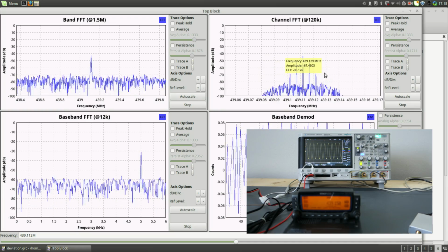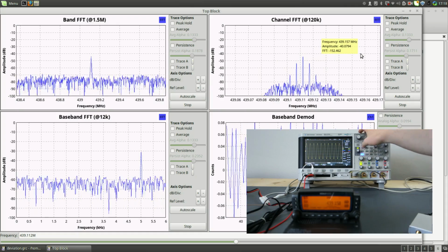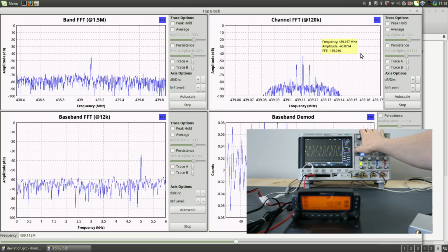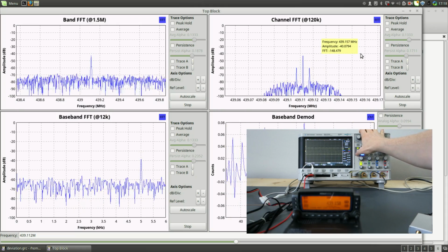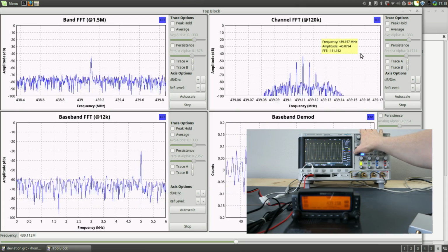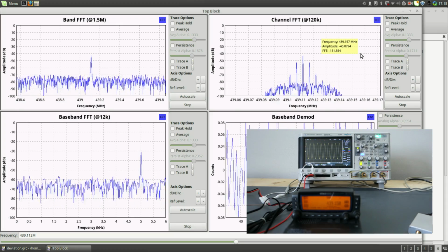and minus 10 kilohertz. And if I play with the amplitude of the modulation signal and reduce it, you can see that there's funny things going on with the sidebands. They sort of rise. The higher the amplitude, the more sidebands I have, but the spacing does not change.